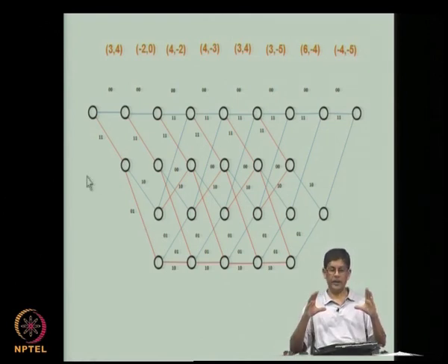What we are aiming for is the inner product between the plus minus 1 version of the code word and the entire received vector, but we will actually do it a branch at a time. It is clear from the nature of the inner product that you can compute inner products per branch and then add them up along all the branches making up a path, and that way you get the inner product for the entire path, right. So that is clear. That is what we are going to do. So I am just going to simply write down these inner products.